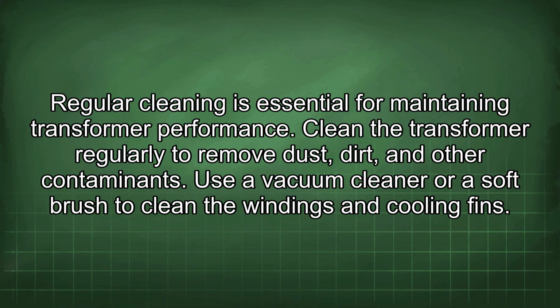Regular cleaning is essential for maintaining transformer performance. Clean the transformer regularly to remove dust, dirt, and other contaminants. Use a vacuum cleaner or a soft brush to clean the windings and cooling fins.